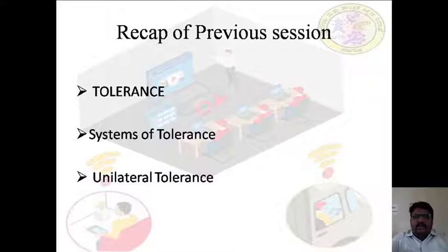Another advantage of this system is that go gauge ends can be standardized, as the holes of different tolerance grades have the same lower limit and all the shafts have the same upper limit. This form of tolerance greatly assists the operator when machining mating parts. The operator machines to the upper limit of the shaft, knowing fully well that he still has some margin left for machining before the parts are rejected.